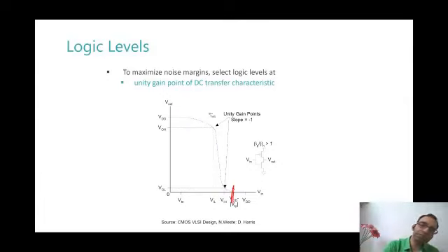Should I start to call noise margin from here until here, or from where to where? So a typical definition that is used is that in this transfer characteristic, the points where I have a unity slope from 0 to 1 and 1 to 0 side, the region between them is the intermediate region, and I have the remaining part as noise margin.